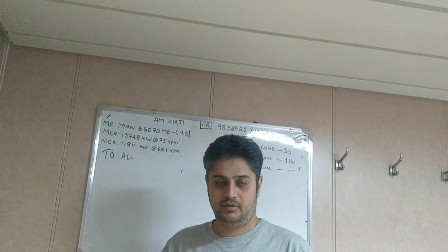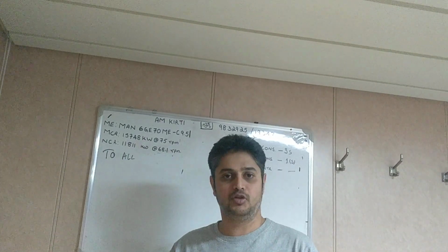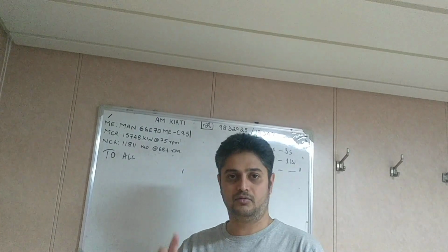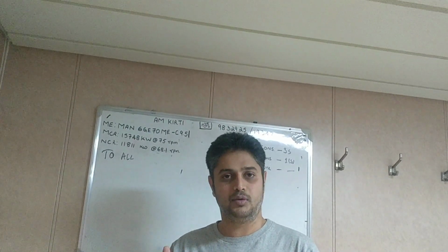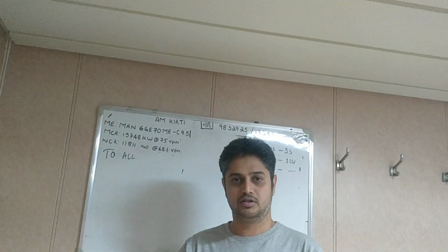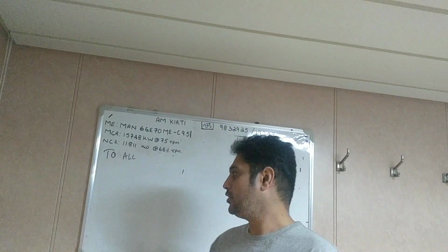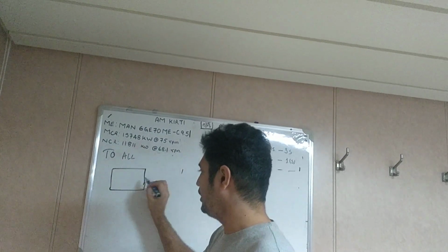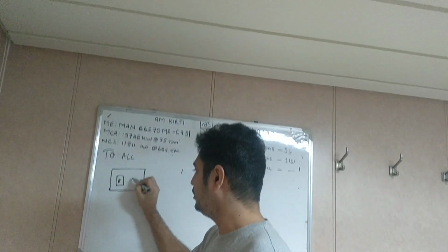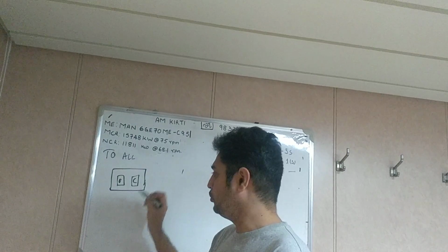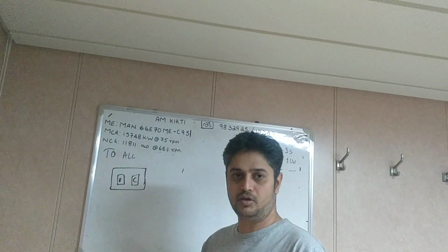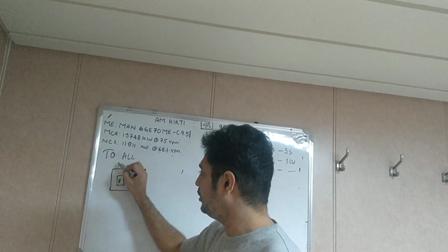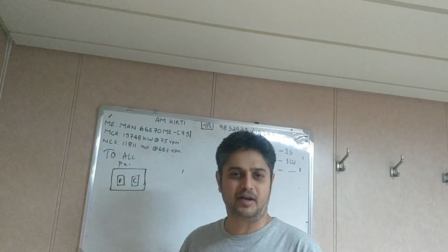Usually in the ship's office, in some ships you will have operations by computer where you have to click for open or close, and in some ships you have buttons or switches for open and close. Assuming you have a computer where you have selected a valve, it will open or close. If you click, you will also have an option for how much percent to open. Suppose this is the computer, the VRCS panel basically.